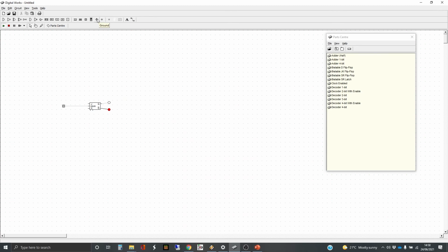So that's a constant 0. This is a constant 1, which is VCC, which basically means plus voltage. Connect it to both those. And instead of using this as an enable thing we can put up and down, I'm actually going to connect it to a clock to show this working. And that clock's running, and we can see as it goes, it switches between one and the other.